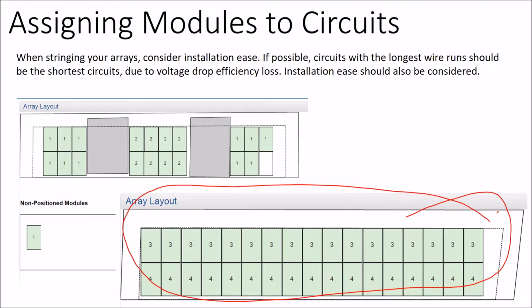Because with microinverter systems, every module on the roof is effectively its own solar array that's tied into the grid along that branch circuit. With DC optimizers, it's the same way. You can have strings of different lengths, panels facing different directions. But even so, you'll have branch circuits for microinverters, strings for DC optimizers, strings for string inverters.